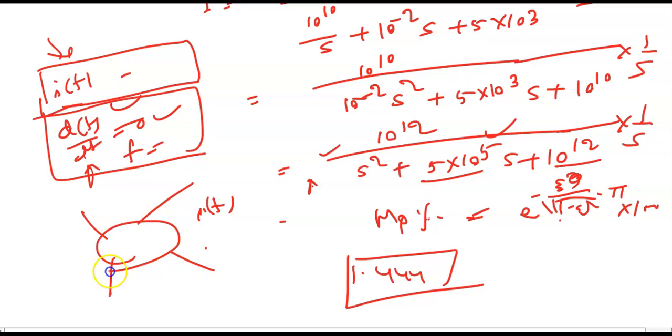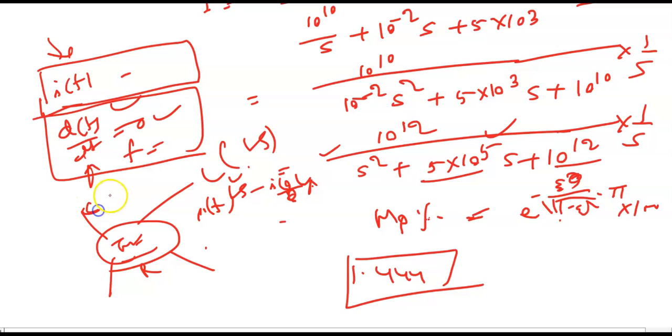Suppose you have, let's say, transient analysis. Here L, here C, here R, like this. L will be Ls, and if there is an initial current, it is Ls minus I0 L for the voltage transform. If it is a capacitor, it is 1 upon Cs plus V0 upon s. Just try to do this analysis, and definitely it will be very helpful